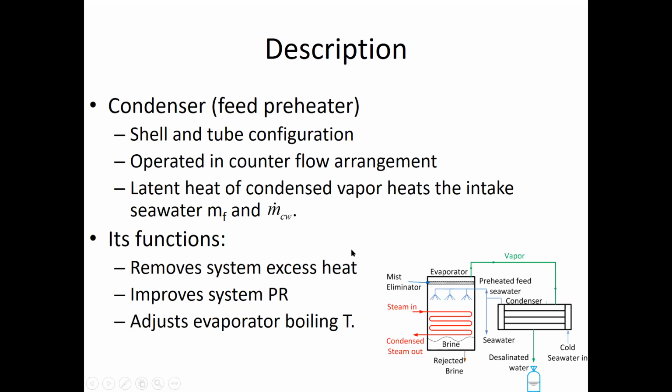The condenser or the preheater, usually it's a shell and tube heat exchanger operating in a counterflow arrangement, where the latent heat of condensation of the vapor is the source of heat that is used to preheat the seawater and definitely condense the vapor there.